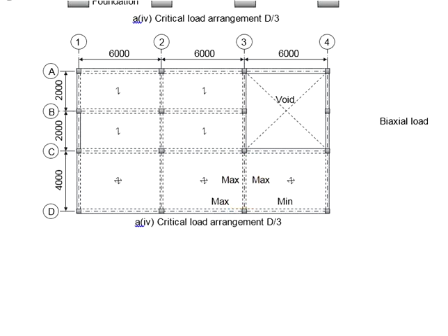For that, you will need the maximum load for the slab here and also the maximum load for the slab here. At the end of the day, you will expect the bending in the major axis and also bending in the minor axis. So, this column will be the biaxial loading column.